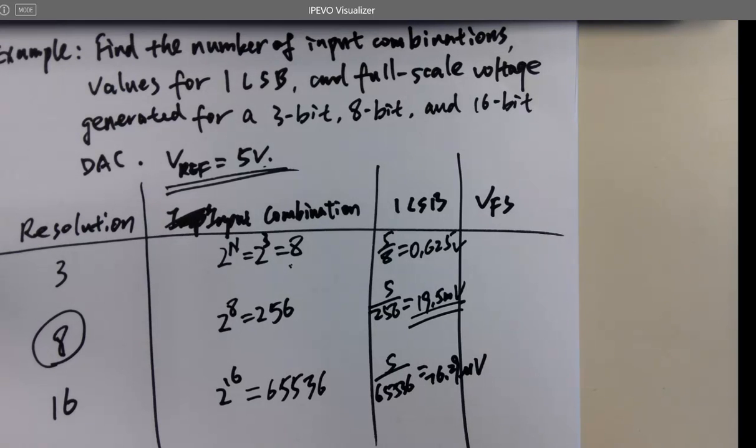So once pre-amplified, you're probably getting 1 volt or a couple hundred millivolts, and then you amplify it again with your own amplifier. Then it's very easy to handle because it's already at the 100 millivolt level. You can easily display it. If you don't amplify, it's okay; you can still display it on the oscilloscope.